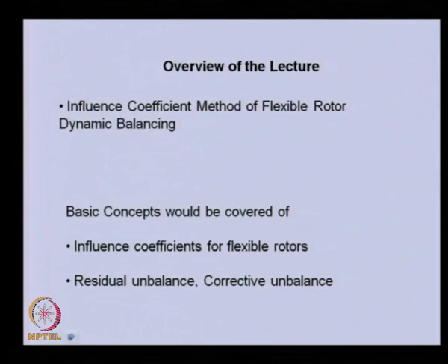The overall overview of the lecture is that we will be describing the influence coefficient method for flexible rotor balancing, especially the dynamic balancing of rotors. Apart from the concept of the influence coefficient for a flexible rotor, which is slightly different compared to the rigid rotor case we described previously, we will also use terminology such as residual unbalance and corrective unbalance in the present analysis.